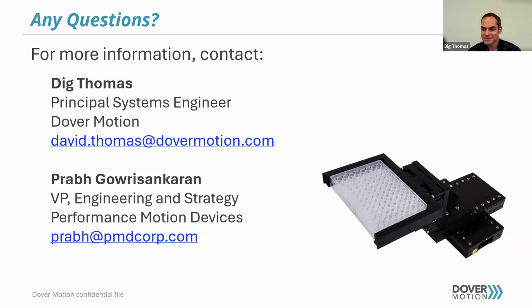Another one here. What is the best way to coordinate my hardware autofocus with the stage motion? So typically what we recommend here at Dover is, if your autofocus device offers step and direction or quadrature output, since these are both digital signals, you don't have to worry about any signal corruption, to feed those into the electronic gearing mode on either the DOF5 or Smart Stage Z.